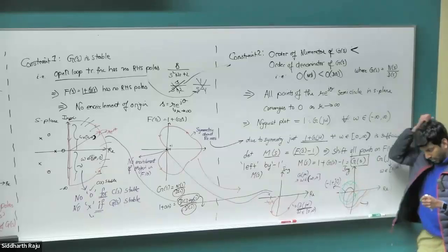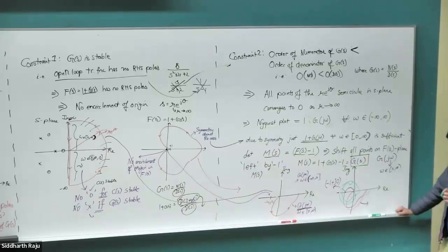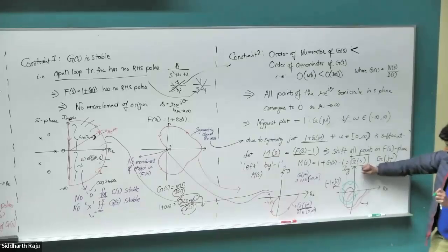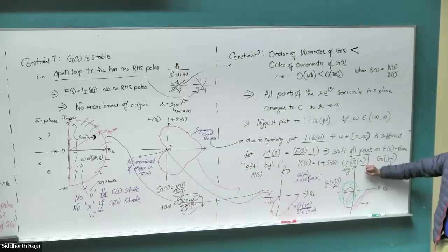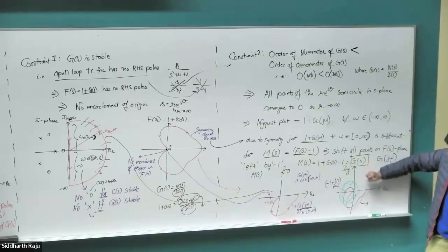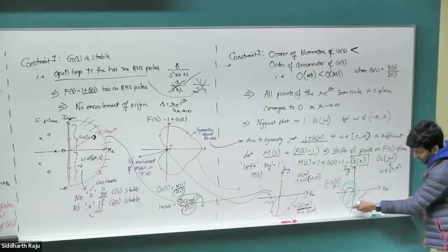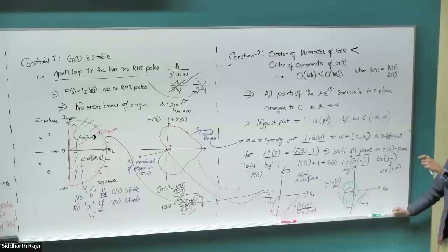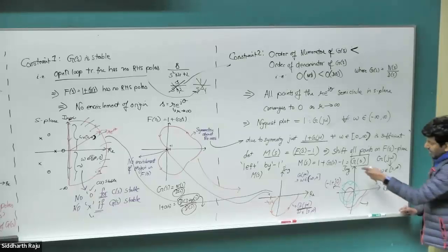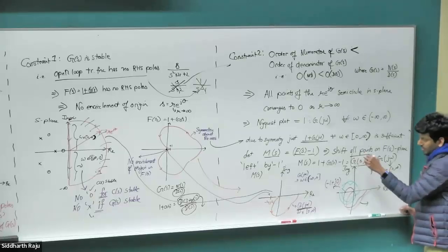So the idea that I want to take away from this is, if I am given some transfer function that is closed loop stable, and there is some kind of measurement going on in the system that has some delay, then any time delay that we have here is basically the three curves that I've drawn. The more time delay I add into the system, the more phase lag that becomes in the frequency domain, right? We will look at that in a little more detail when we write down the equations, but that's the overall idea.